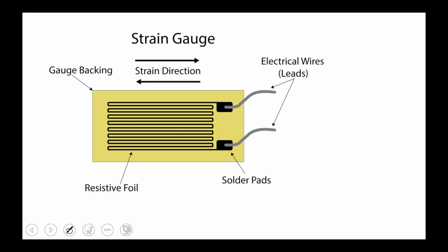So this is the schematic of the strain gauge sensor. These are the electrical wire leads. We have to supply some external power supply, either 1 volt, 2 volt, 3 volt operating bias voltage. These electrodes are made of gold, and these are the layers through which we get the strain direction. So when we place something here and here, as pressure sensors, it will change the resistance.